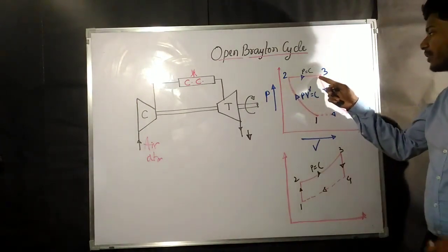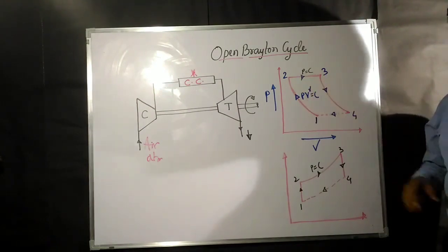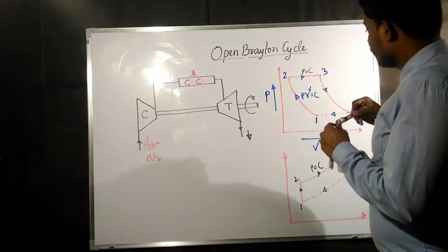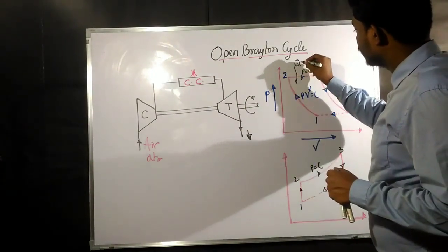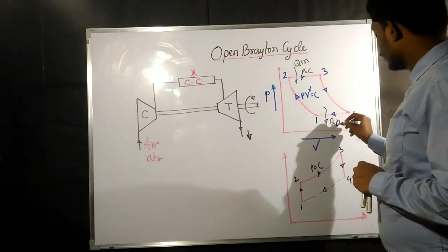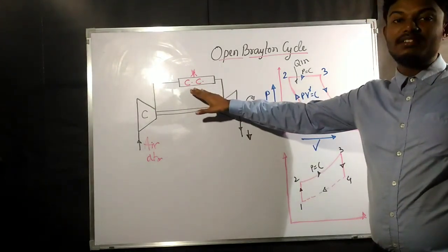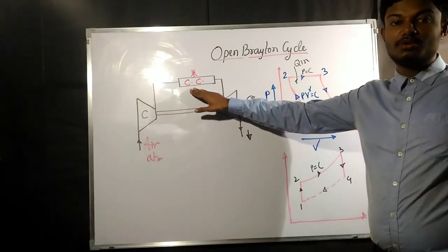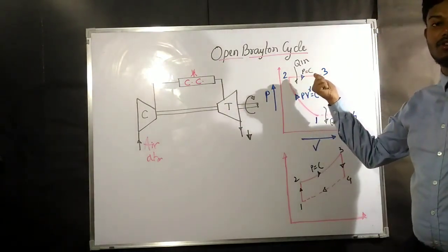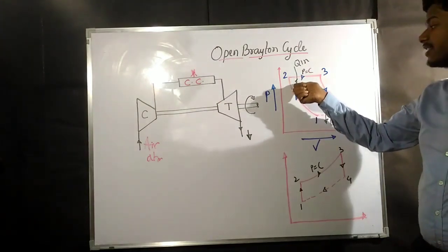After that, keeping the pressure constant, the heat addition takes place. So this process is at constant pressure, and this process is nothing but our heat addition process, Q in. And this is our Q out, or Q rejected. In the assumptions we have already said that whatever combustion process is there is going to be replaced with the equivalent heat addition from an external source.